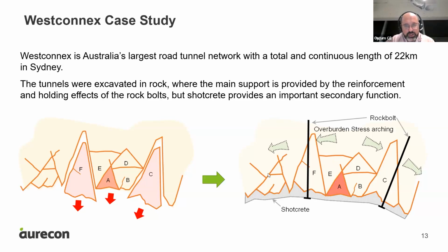How do you check crack width? In the model, I can get crack width. The model is, as I said, a mere crack model. Once it cracks, the model puts a plane where all the plasticity will be concentrated, based on deformations in reference to that plane. How much that crack, or plane of weakness, starts opening gives me the development of the crack width. So I can get crack width as an output. In the testing, I measured those too.